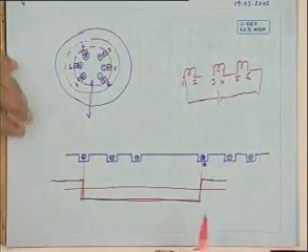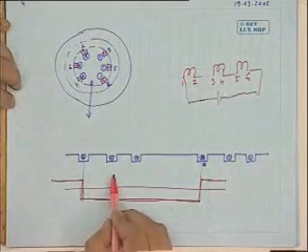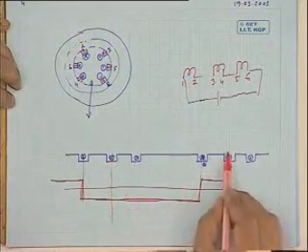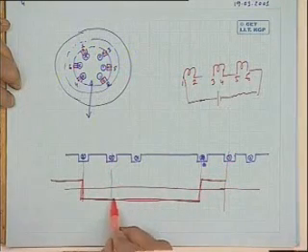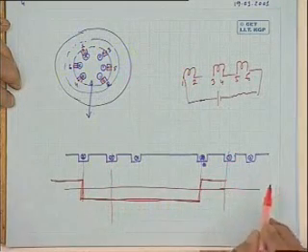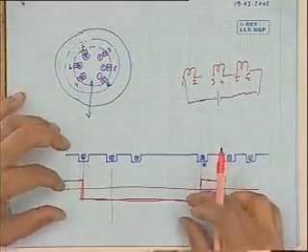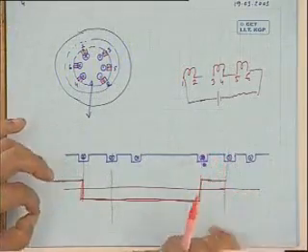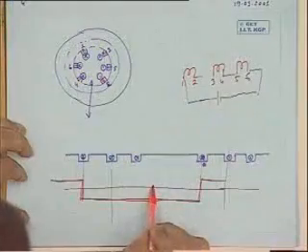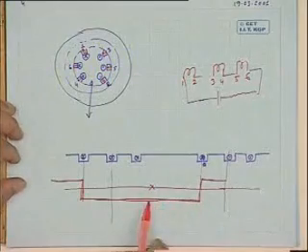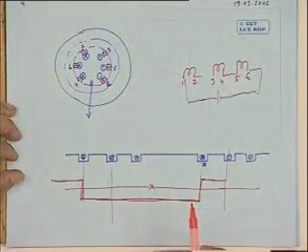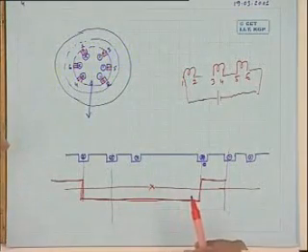It will be like this for this slot. Next slot will be similar. This and this will produce similar MMF, but it will be shifted by this one, rectangular. Then what you should do? You should add them point by point. At a particular position, I know in space what is the net resultant field. I will add these 3.